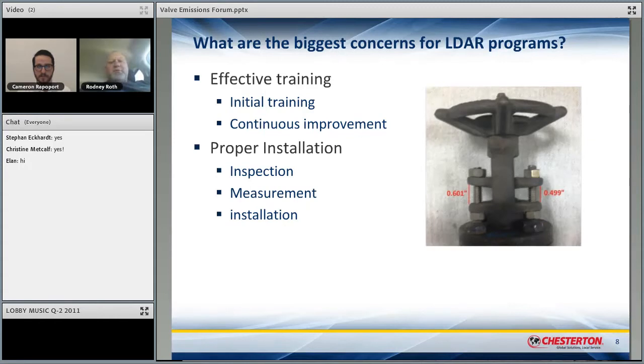And so you have to train the personnel to understand all aspects. And that doesn't just mean training plant personnel. That could be training in-plant personnel, contract personnel in the plant, or also we could be training third-party repair contractors such as United Valve or Southern Valve Services or DK Image or companies around the country that are doing valve repair to ensure that they're installing packing correctly and maintaining the stuffing box and stem to the finishes that we need so that this program can become a preventative program instead of a reactive program.